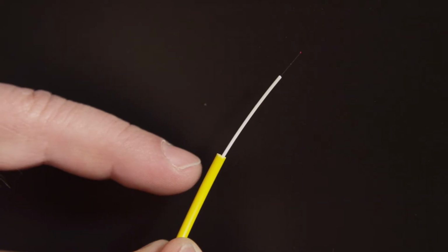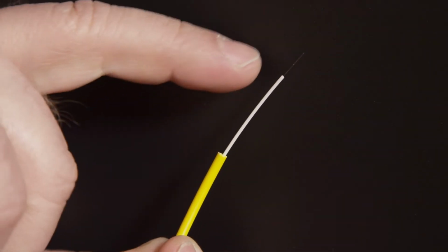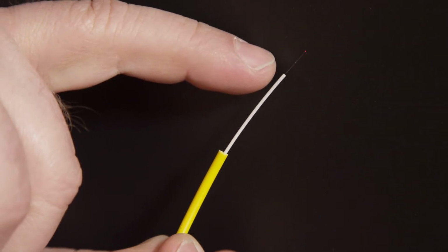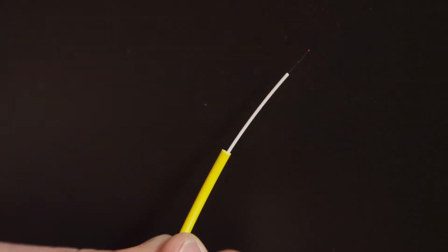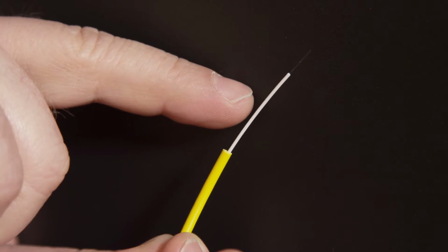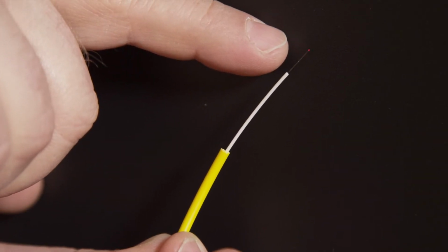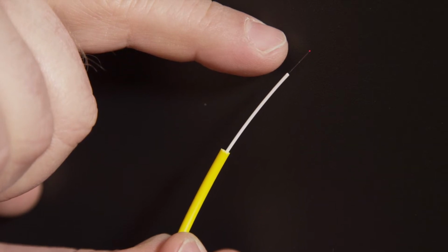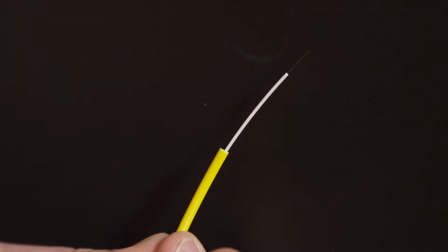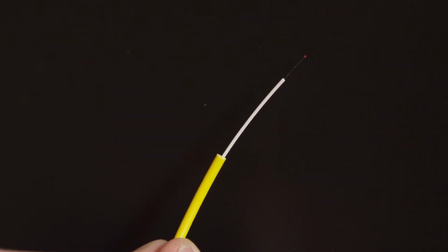The jacket you see around fiber is there to protect it from day-to-day handling. Fiber-optic cabling is basically just a very thin piece of glass through which light is sent. This glass must be carefully protected. If you strip back the jacket of these fibers, you will see a smaller cable inside. And if you remove the plastic that covers this smaller cable, you'll see the tiny strand of glass that is the fiber-optic cable. That strand of glass is capable of sending hundreds of gigabits per second of information over tens of kilometers, but it is also extremely fragile.